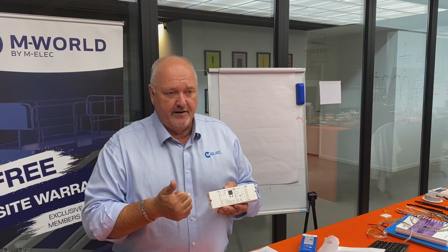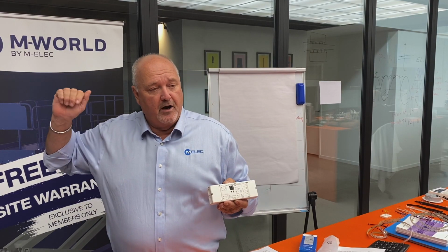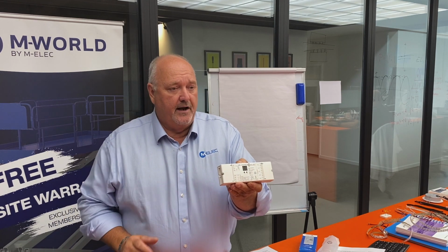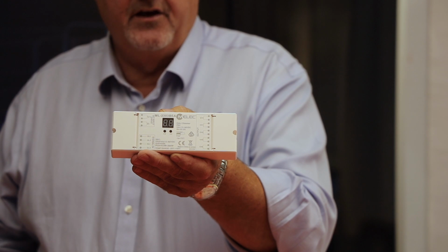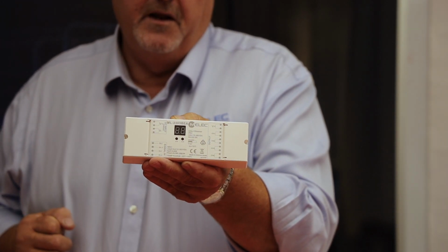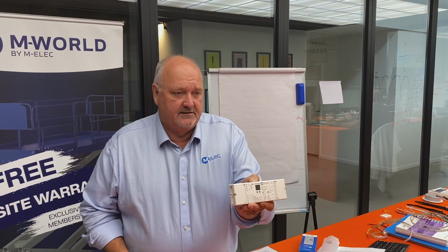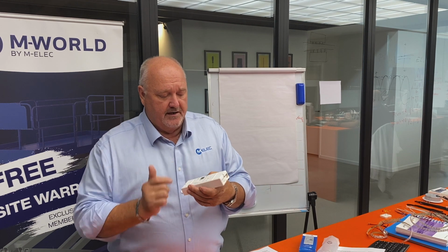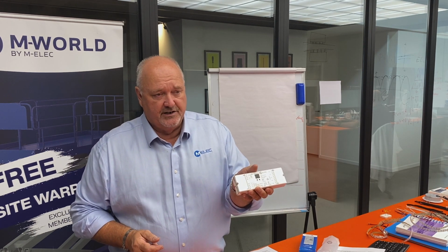Through this window here, I can program it and give it an address, which means from when I program my DALI system, I can tell this to do whatever I want it to do. I can tell it to turn on. We can have sensors that control it because everything works on a DALI bus. This is 4 channels, so I can do RGBW, or just a single channel if I want, or I can have 4 DALI inputs controlling 4 different strips of LED.